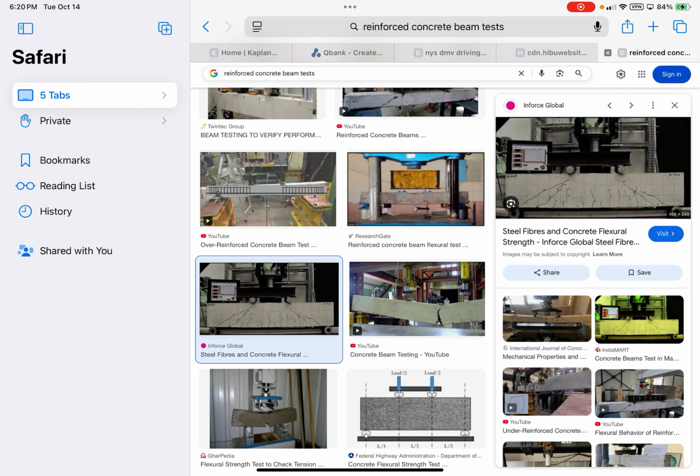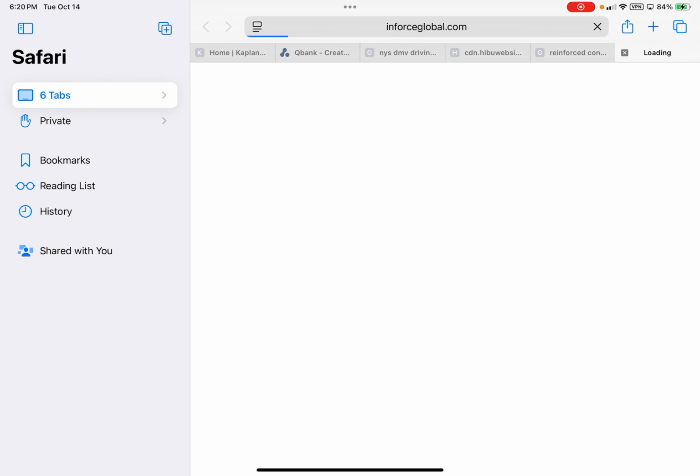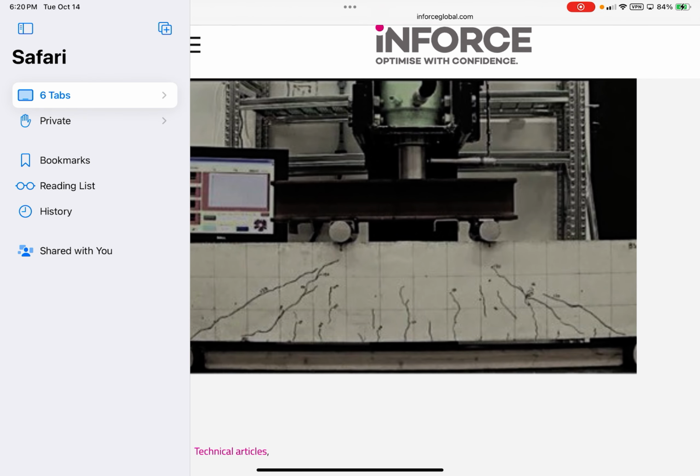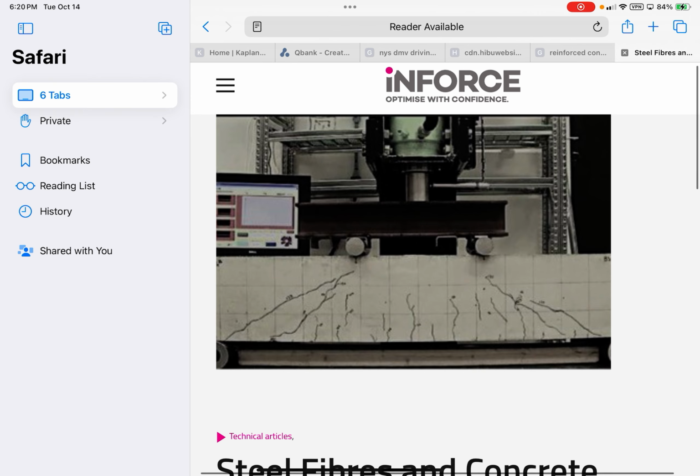And that's a horrible picture. Here we go. You can kind of see the crack development. How does it fail? You see where all of the cracks are developing? It's going to fail along those crack lines, so it's important to understand what the stresses are along those crack planes.